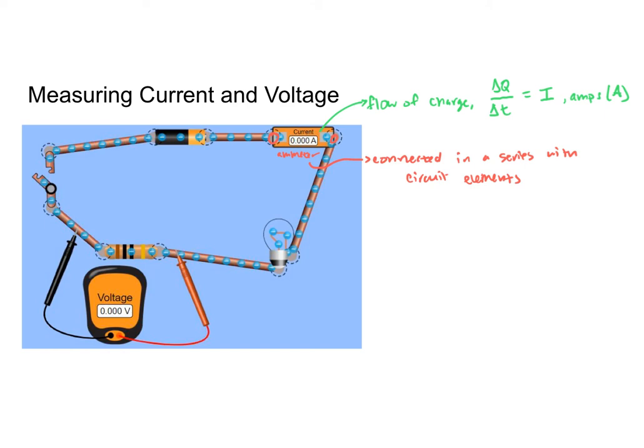And it's very important that we put our ammeter in the circuit itself. Otherwise, our ammeter has a really low resistance. So our electrons are going to try to travel through the ammeter instead of traveling through our bulb and our resistor if we put it in our circuit the way we have our voltmeter here. And that brings us actually to our voltmeter.